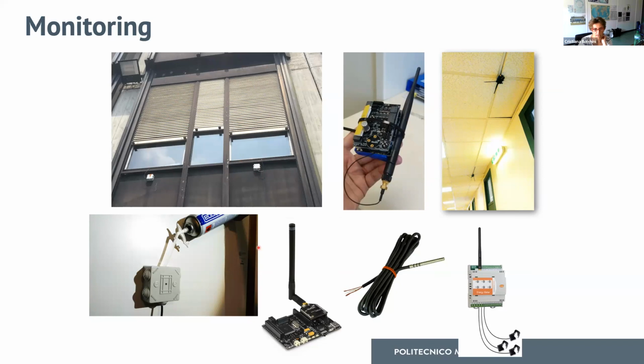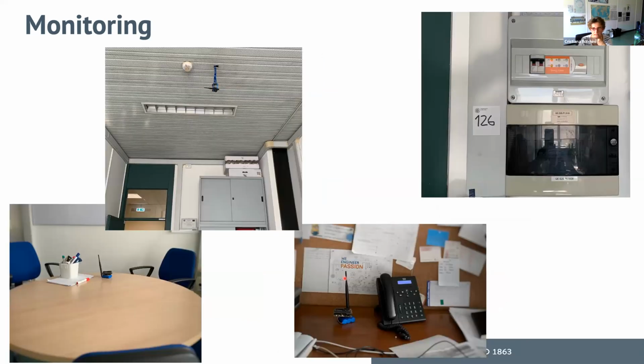And these are the sensors that have been deployed inside the building, in the corridor or in the rooms. The bottom right element here is instead the energy monitor that tracks where the energy is spent within the air conditioning, the lighting, or the energy for supporting the electronics inside the offices and the elements. This is the setup of the office. So you see at the ceiling level a sensor, and on the table another one, with some kind of redundancy to make sure that we are not missing information.